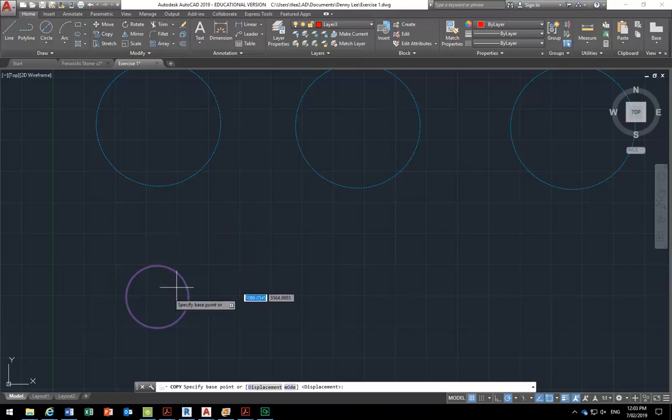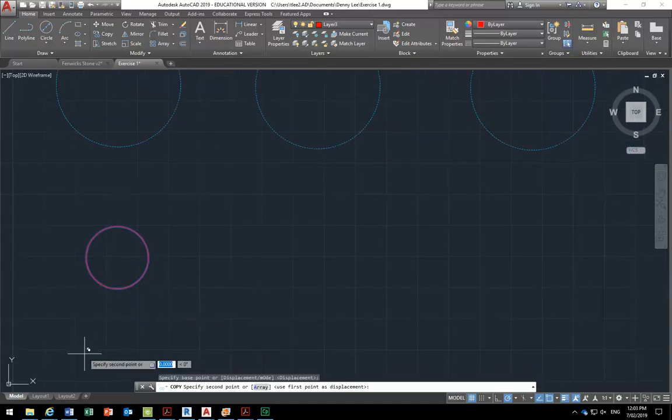So essentially the base point could be the centre, but it's important that you realise the base point can be anywhere. And it's actually a bad habit: a lot of people who don't really know tend to use points on the object they're copying and really limit what they're trying to do, when the base point's a really useful thing. It can be anywhere else. So I'll just show you, it can be down here. Doesn't matter. The important thing is where we go from there.